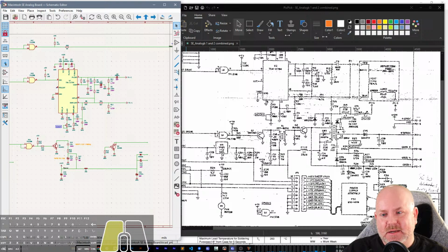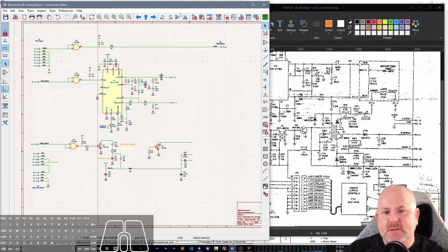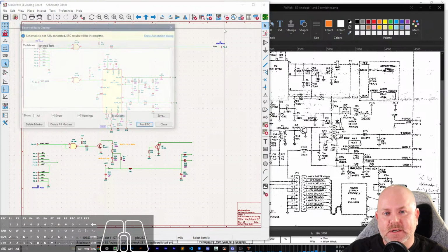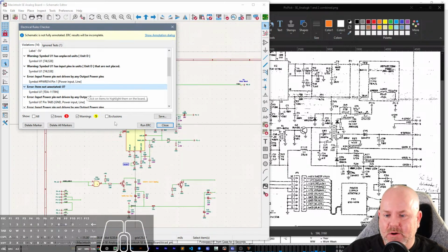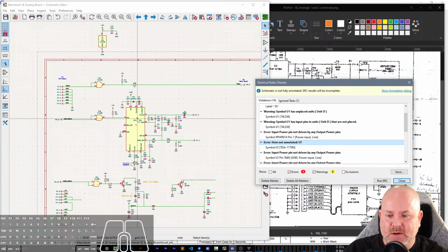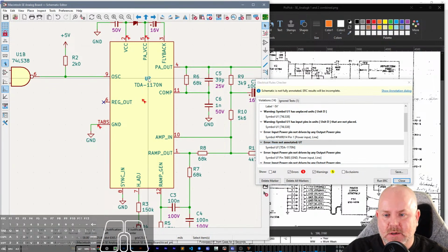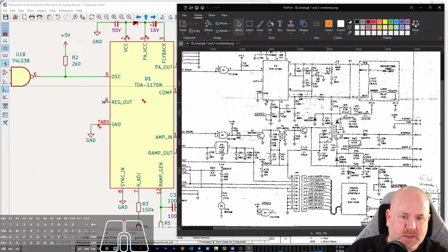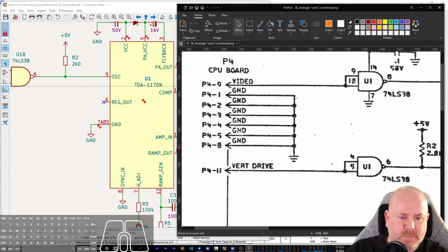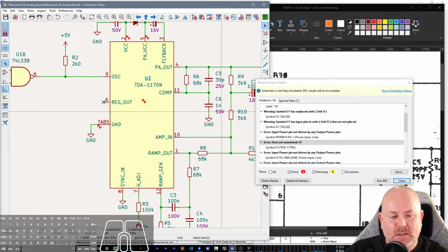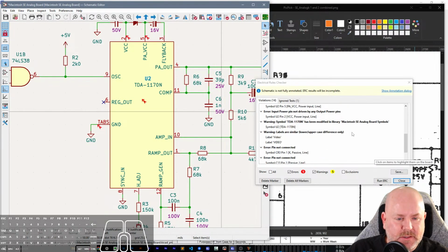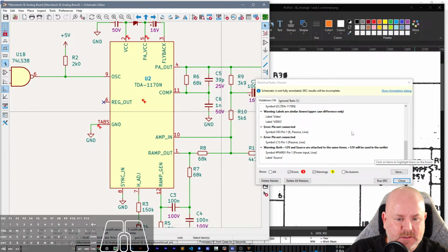So I'm not going to try running. Well, you know what I will at least do is, let's see, if I try to run D or C, I want to know what's not annotated. Let's get that done right now. So this is U1. I already know that. Well, I'm going to double check just in case I'm wrong. I thought I was wrong. Yep. Good thing I checked. That was U2. Input pin. Let's see. Not connected. That is the only thing that is not annotated, right?